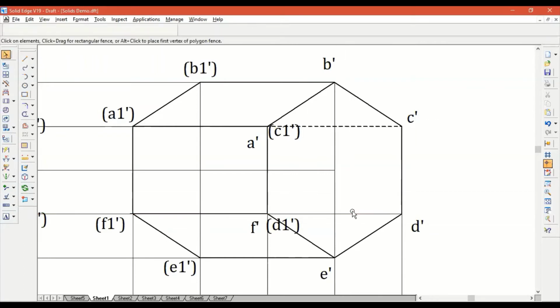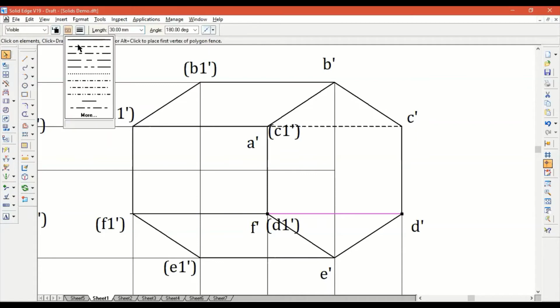The other thing you have to also know is whenever two lines intersect, one of them is always going to be invisible. In this particular case, CC1 is intersecting with AA1. We know that AA1 is visible. We also know that AP is visible, and we also know that AF is visible. So we have four lines intersecting, of which 3 lines are visible. So obviously, CC1 is going to be invisible. And the same hypothesis holds true for the other point, DD1, which you're going to mark in a discontinuous manner.